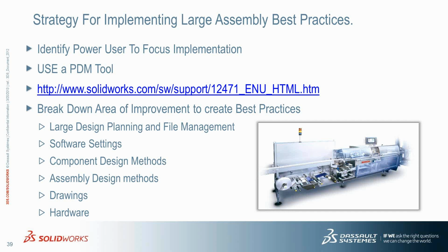And the second part, we're going to make sure all of our software settings are optimized for performance of large assemblies. And then we implement some assembly design methods. And we make sure our hardware is in place. And you take it in a step-by-step approach, but you create some sort of best practice so you can repeat it. You have somebody new coming in, this is how you do things. We create large assemblies, so this is what you want to do. Okay, it's important.